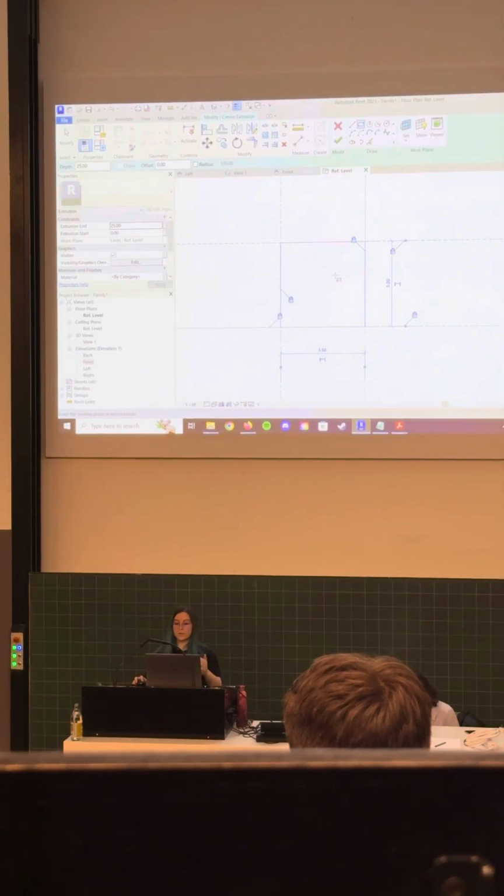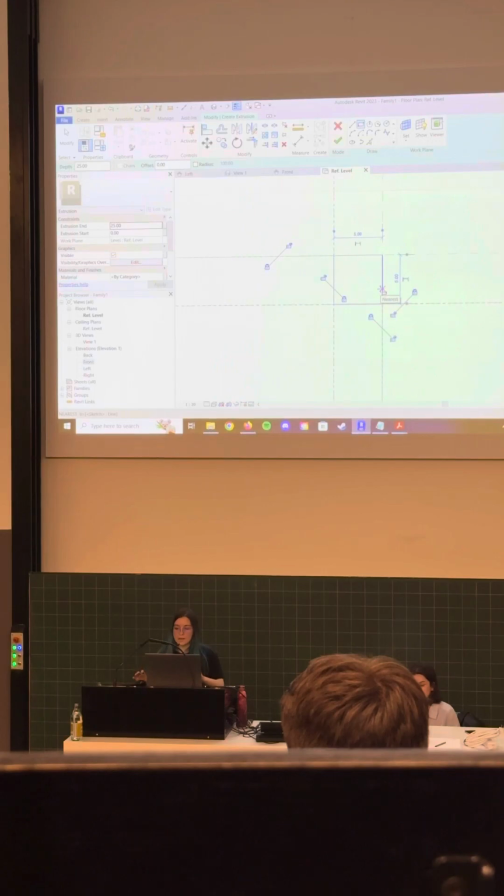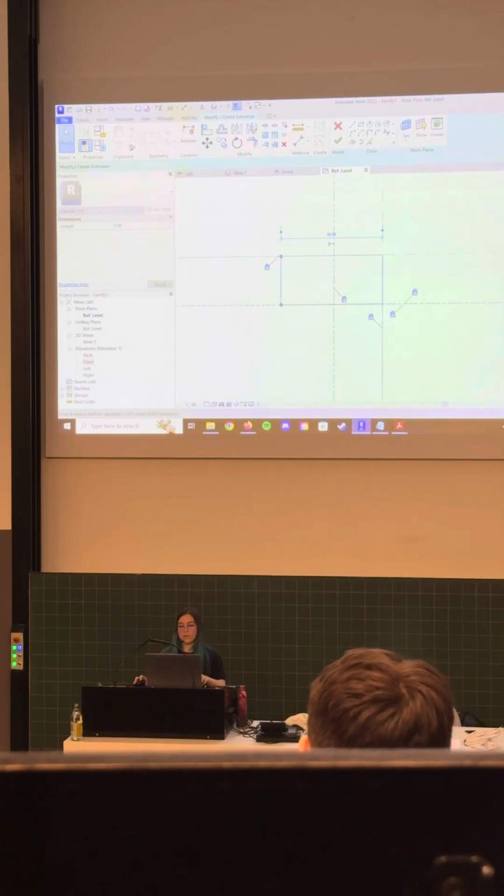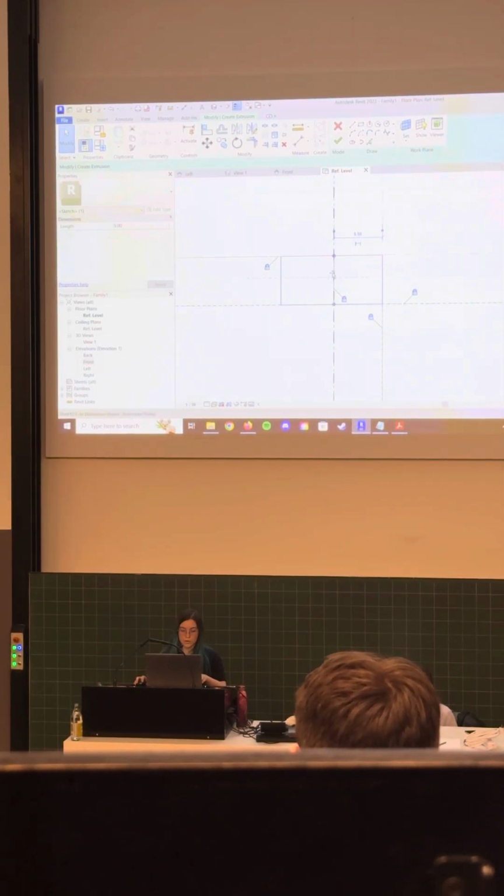If you forget to lock any of these, then the legs of the table will not be constrained to the axis, the reference planes that we created. For example, I'm going to lock this one, and we see what happens since I didn't lock it. And now you see I can change this independently from this reference plane. That is why it's important to lock it in place.